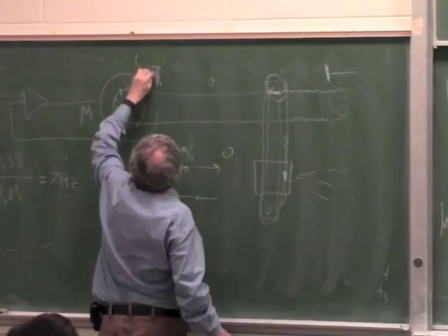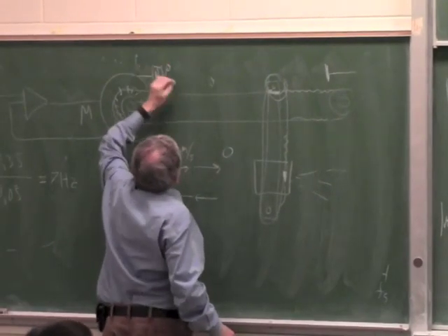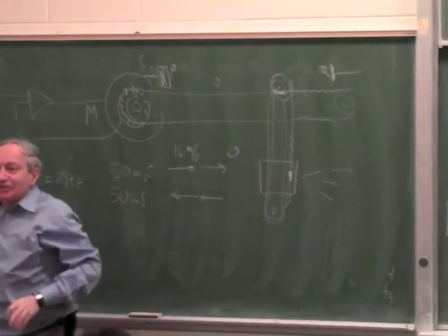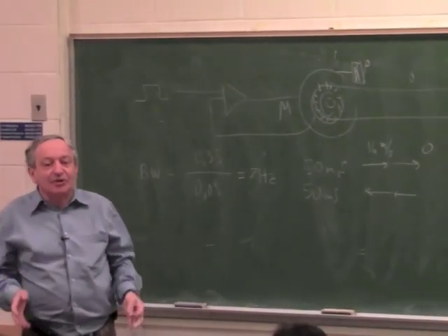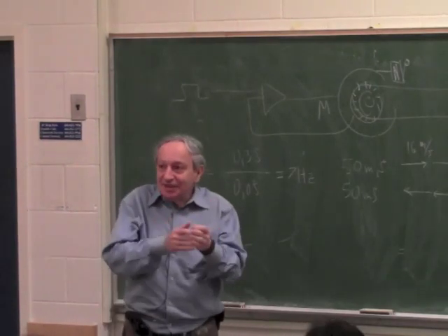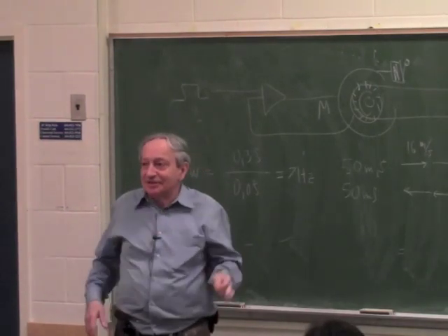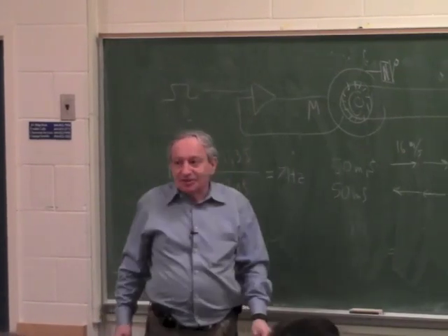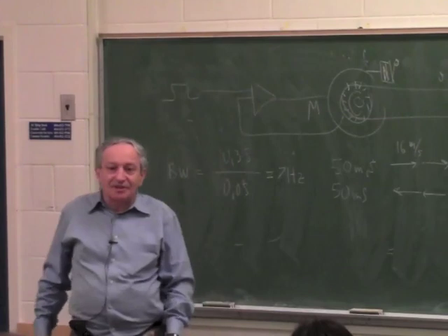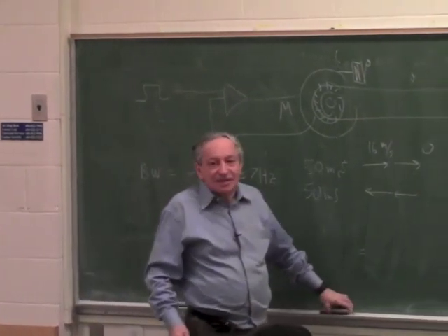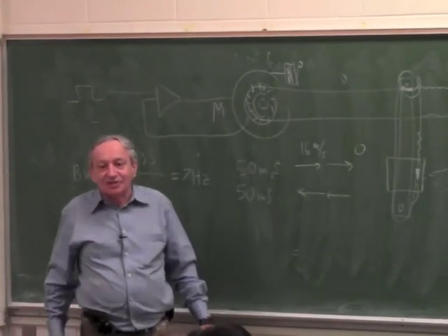They just have a micro switch here, because this sensor doesn't have to be that accurate. It just tells you it's end of travel. So when you turn on a machine like a CNC machine, it always goes to one end, hits the limit switch and says calibrated. And then it measures with a non-absolute sensor.